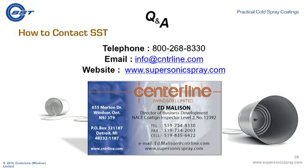From a physics point of view, I could almost unequivocally say that almost every coating is permeable to gas travel. It's just a question of the speed at which gas travels across the coating. Let's think this through. Our coatings are very, very dense, typically less than 0.5% porosity, volume on volume. But if we choose to, we can drop that porosity with some parameter control to less than 0.1. And I think we've designed some coatings with some special materials approaching 100% densification. That's going to provide customers with a fairly impermeable barrier coating between, let's say, the cargo and the vessel wall.